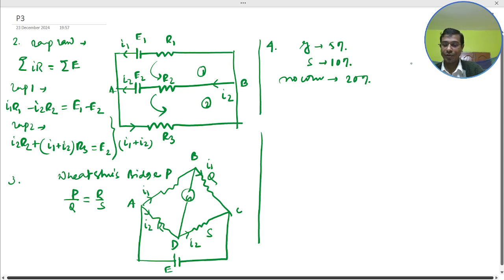So suppose this is a resistor here, this one, with bands 1, 2, 3, 4. The first one defines the first significant digit, the first digit. The second one is the second digit. The third one is the multiplier. The fourth one is the tolerance. Next one,